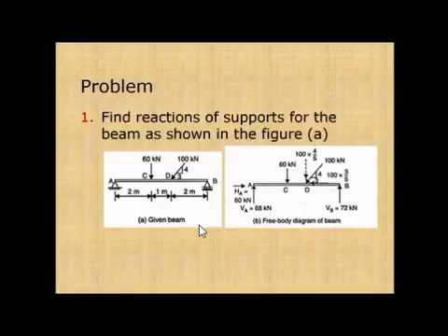So first of all, the first and foremost thing is to draw a free body diagram. So I have taken all these things, pictures and all, from internet. So collectively I can show you all these things, so you will not be harassed searching in internet. Now after drawing the free body diagram, that becomes quite easy. Now as this is a rigid support or a hinge type, in this case we have two forces, that is horizontal and vertical, as I have told you before. And in case of roller type, we have only the roller reaction. Similarly, a force 100 kN is given in this direction, so it can be resolved in two forces.